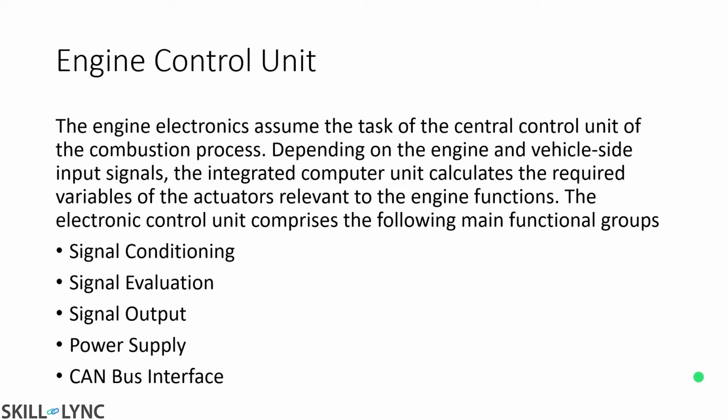So we want a correlation between all these set points, and then we want to see whether the value it is giving us is not garbage. We want to understand if the value that it is giving us makes sense. This is called a rationality check, and we want to see if all the values, however many we get, make sense, and if they have to be related, and then we want to understand what decision has to be made. All this decision is taken by the ECU.